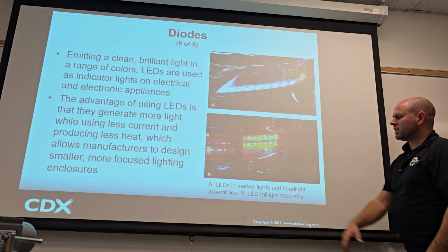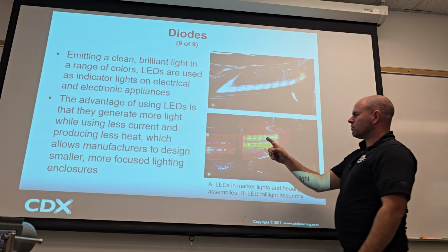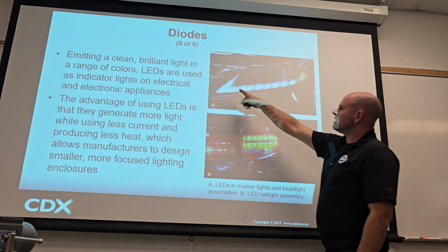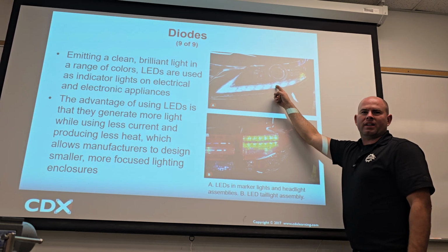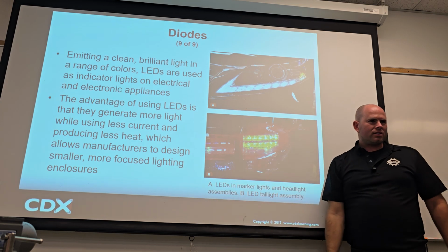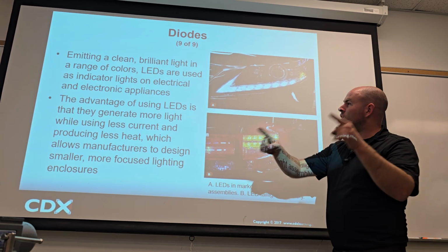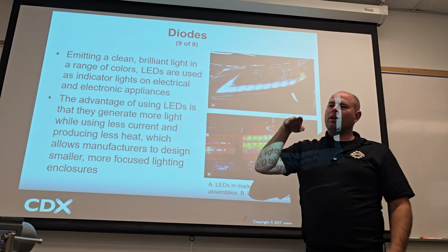And then the taillight's kind of the same. The way we diagnose this is the same as the way we diagnose this. Here's where it can be easy though. Let's say you see all these LEDs working except 3 or 4 of them are out right here. What do you think your diagnosis is? It's going to be the LED light. That's it. It's because we know if some of them are working, it's getting its 12 volts and ground.